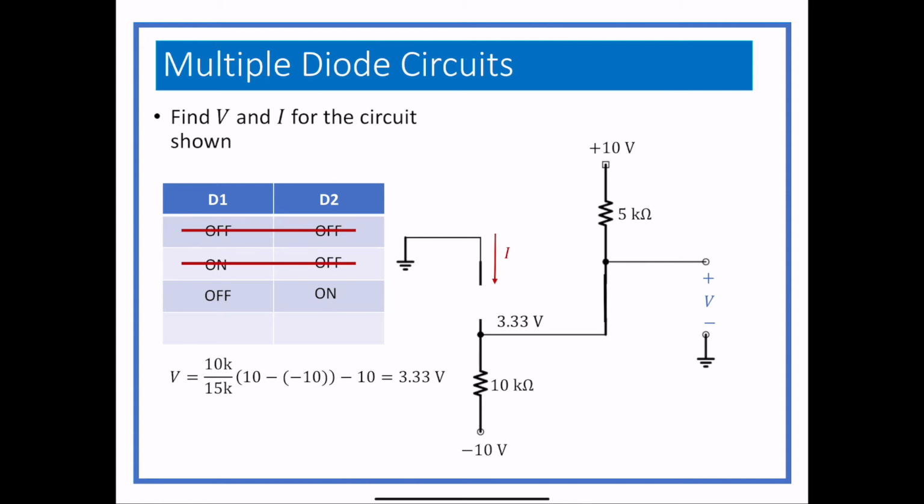So that's why you can't always assume, oh, I know what it's going to be because the last circuit showed me that it would be forward biased. So in this case, D1 is off and D2 is on, just because of the movement of the two resistors, and the current I is just going to be equal to 0 because there is no current in that open circuit. So there's going to be more of these you get to try on Friday. It's maybe like 4 of those you get to try.